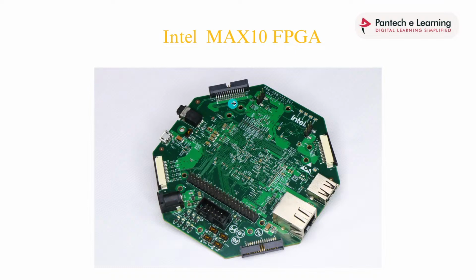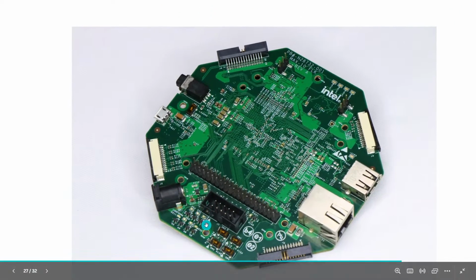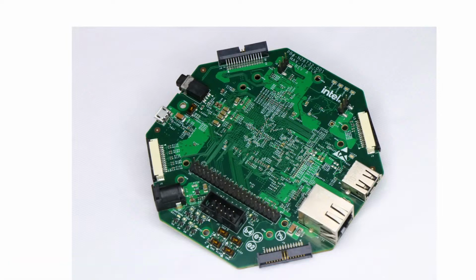There are also I/O pins. We can connect a GSM module or other controllers. We can use the I/O pins for a serial monitor. We can see the output from these I/O pins, and there are separate LEDs, like these are the LEDs. It is visible for you. We can see the LED blinking as required for the specific design. This FPGA can be fully reconfigured. We can dump the code by using the JTAG. This is the JTAG interface, using the USB Blaster.